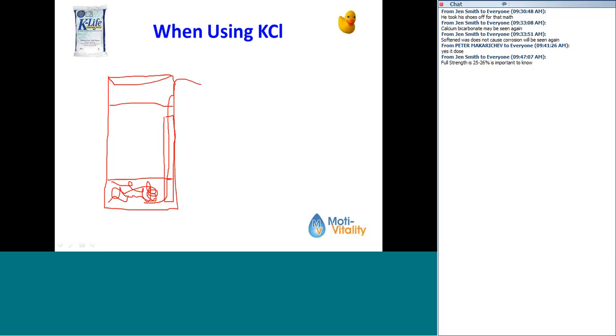But the problem is that sometimes this water level, because this is all dissolved, right? This is a 26% brine saturation down here. So really, really strong salt water. Okay. If any of the water evaporates, there's no more room in the water for the salt to dissolve, so it's going to reform back into its crystal, because the water's evaporated or for whatever reason it's left.